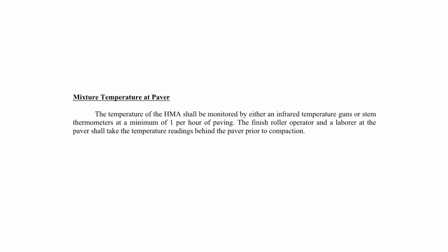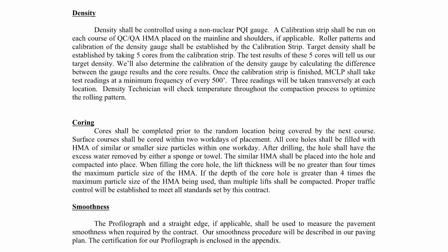Mixture, addressing the paver temperature, or the temperature of the mat at the paver. So the QC technician, whether it's a laborer or operator, whoever, is testing the equipment or testing the mix for temperature, how you're doing your density, addressing the calibration strips, coring, and how we're going to fill in core holes. That all needs to be addressed in your QCP.